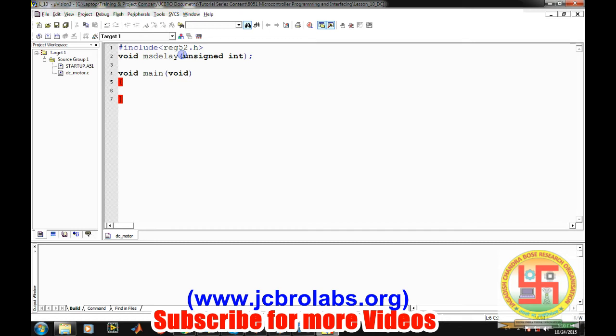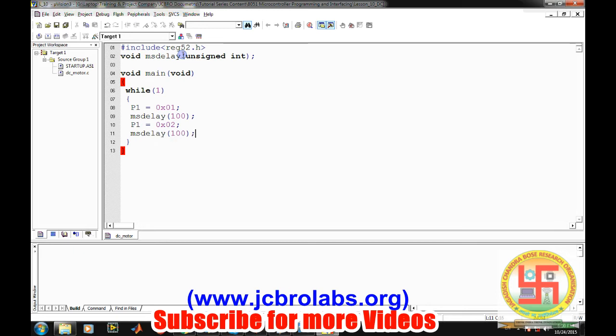So first we'll write a simple while loop. We are not taking any input, so we don't define anything. It's very simple. We'll write P1 equals 0x01, and then we'll call ms delay 100, and then P1 equals 0x02. If you are directly watching this video, you can see our previous videos, lesson 9 or lesson 8, for learning how to write this embedded C code. So it's done.